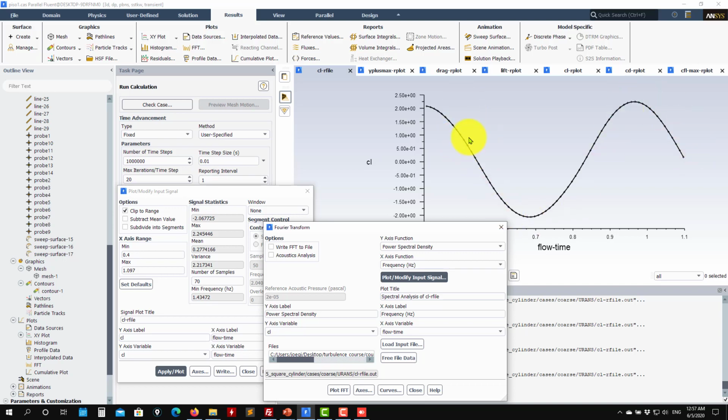Let's say that the absolute minimum number of points that you need to resolve the period will be something about 30, for your time step. We are at 0.5, 0.01 was okay, and the one at 0.001 was even better. You are doing a much better sample. But also this is telling us that now we're going to save the solution, just to show you that you're saving frequency, okay?